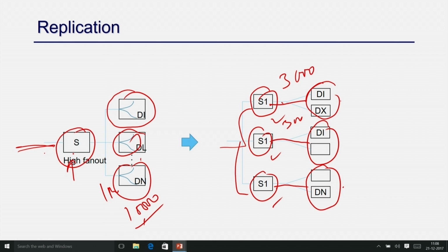It is very obvious that whenever there is a hierarchy in your design, all these nodes are somewhat connected, and the synthesis tool tries to place those nodes inside a particular hierarchy in close by places. So, if you put one hierarchy to the same source, then there is a high chance that all these things will be placed in nearby places, right. So, that is very important.